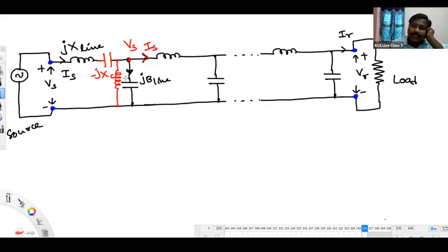How is the admittance of a shunt reactor, plus j or minus j? The admittance of a shunt reactor will be minus j. So it will be minus jBR. You try to match that BR and B line as equal, so that the overall admittance will be zero, and the outgoing current will be exactly equal to Is.